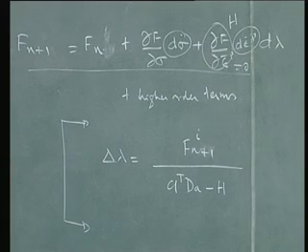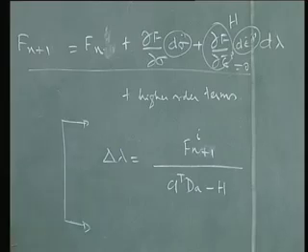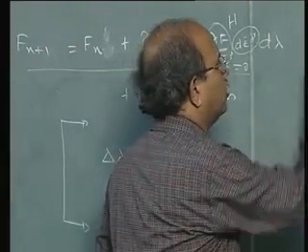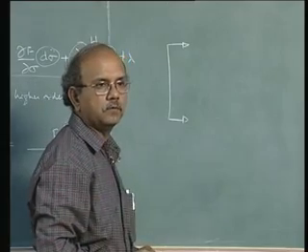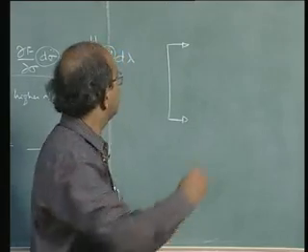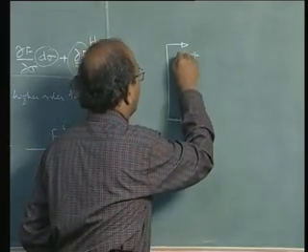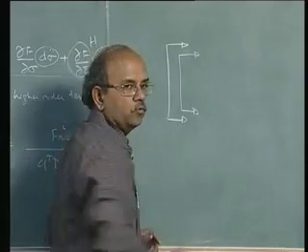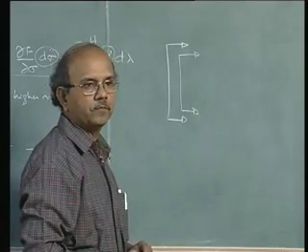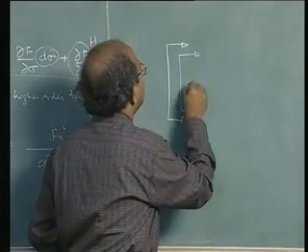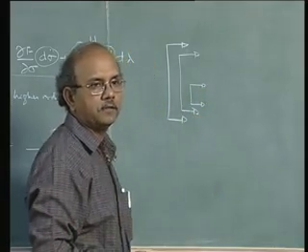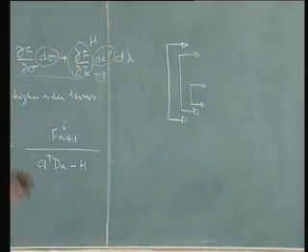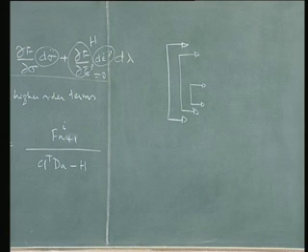I would like you to fill it up. Just one comment. In other words, we have now 3 loops. One is the large incremental loop, okay, for time step. Within a time step, one large iterative loop for it to converge. And within the iterative loop, you have one more iterative loop for the stress update, in order that ultimately my consistency condition is satisfied.